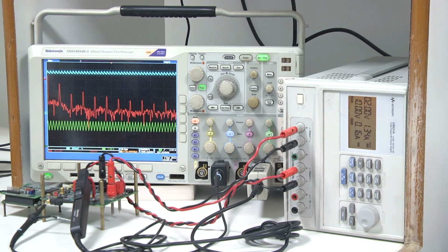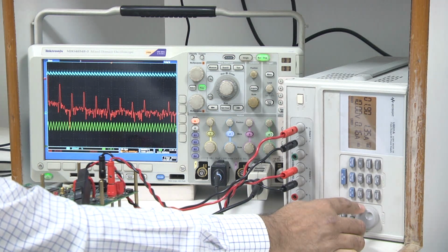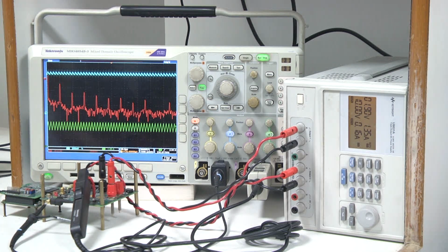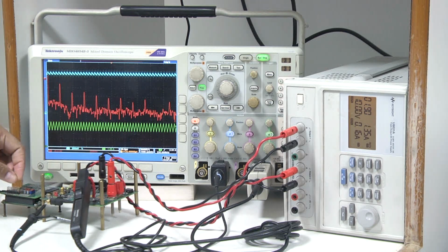So the switching frequency is inversely proportional to the input voltage, and as a result the peak is shifting, but it is perfectly stable. And if you go to 1.9, it is also perfectly stable, and the frequency is further increased. So now 250 kilohertz is the effective switching frequency. So what we learned is that in constant on time current mode control, the valley current is fixed and the current loop is perfectly stable irrespective of the duty ratio, but the frequency is varying as well as the ripple is varying.